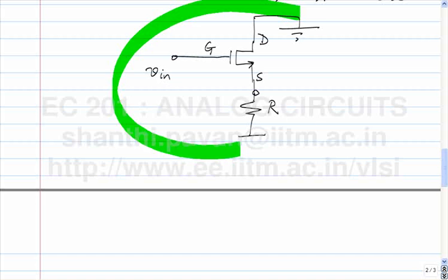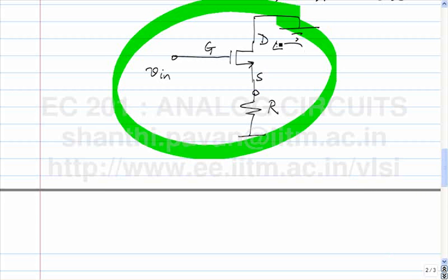This here represents the incremental circuit of a voltage controlled current source, where the incremental output current I out is given by the input incremental voltage divided by R. If Gm is large, does anybody see a similarity between this and the common drain? The same thing, except that in the common drain, the output is taken at the source. Here we are tapping the current through the transistor.